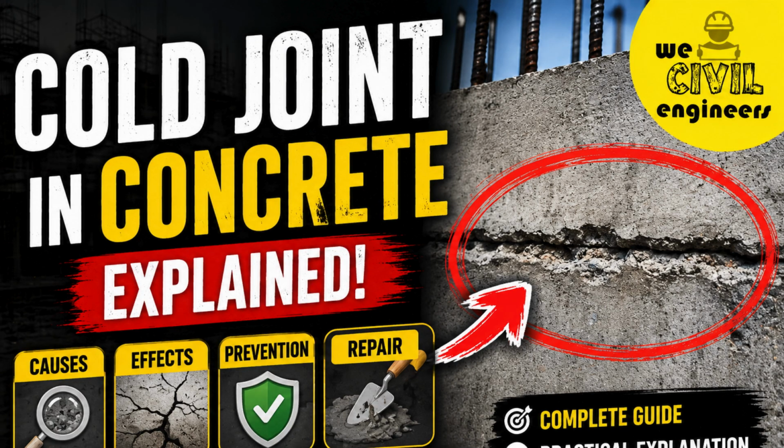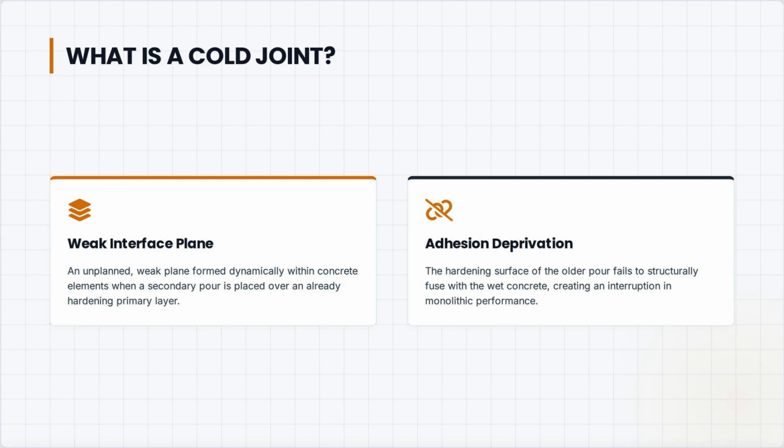In today's video, we will understand what cold joints are, why they occur, their effects on structures, and how engineers prevent them at the site. A cold joint forms when fresh concrete is poured over concrete that has already started setting. Because proper bonding does not occur, the structure behaves like two separate layers instead of one solid unit. This creates a weak interface inside the concrete.